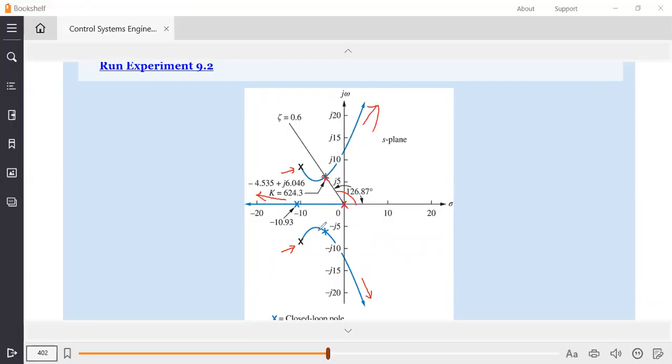Whether you have noticed the difference here or not, here we have changed the gain twice. For the minor loop, we changed the value of gain kf. Then we find the suitable starting point for the major loop. Then we change the value of k, and find the intersection point, which gives us the desired operating point.